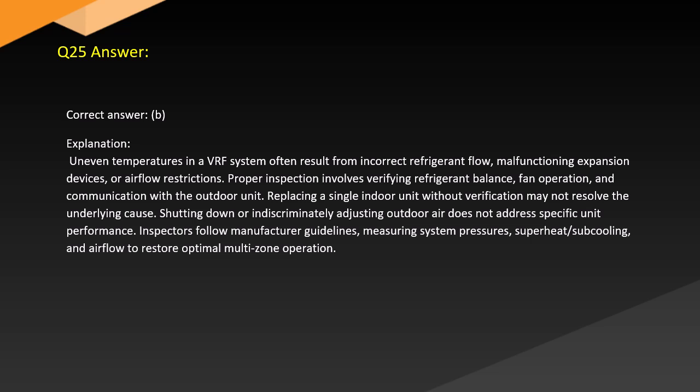Replacing a single indoor unit without verification may not resolve the underlying cause. Shutting down or indiscriminately adjusting outdoor air does not improve specific unit performance. Inspectors follow manufacturer guidelines, measuring system pressures, superheat, subcooling, and airflow to restore optimal multi-zone operation.